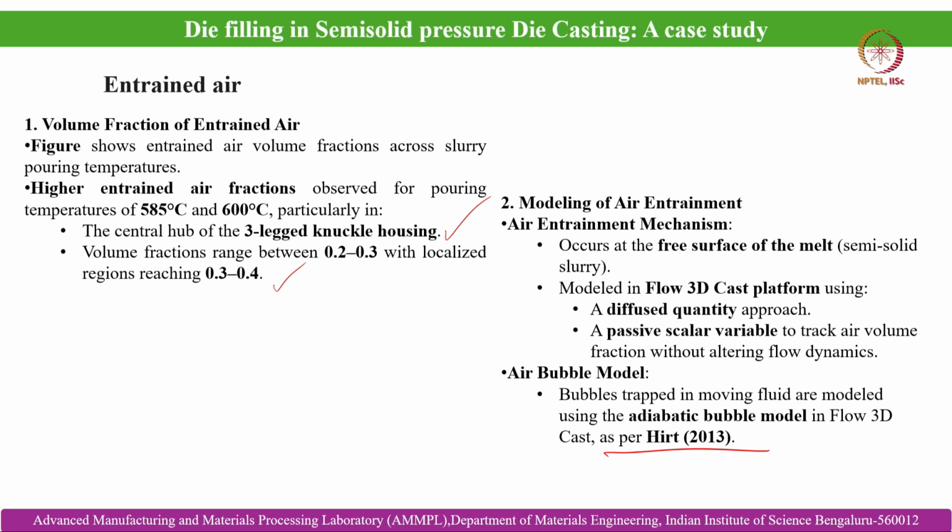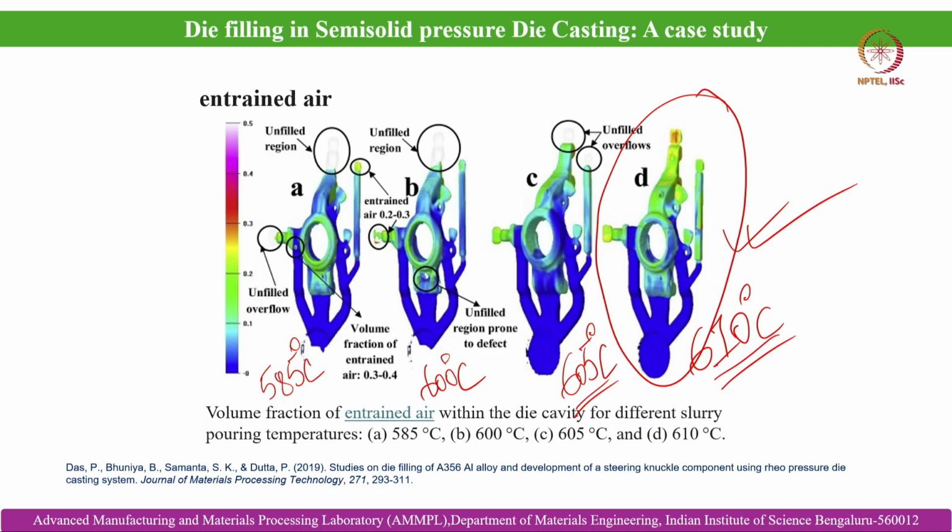Earlier in this section we have already discussed the porosity formation model. So I hope now you can understand how this is useful to model the actual entrained air and also bubble formation during actual die filling studies of a component, by which we can optimize both the design attributes of the component and component cavity and also the process attributes, to achieve the desired component with the desired quality characteristics, the microstructure and mechanical properties.